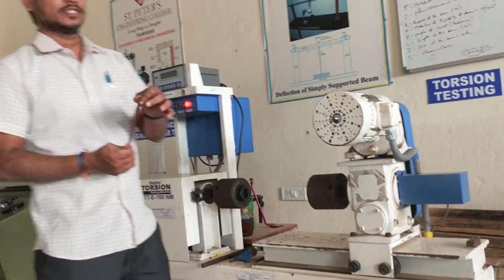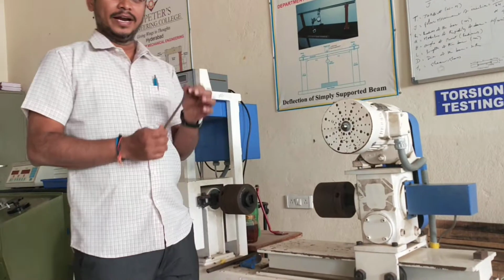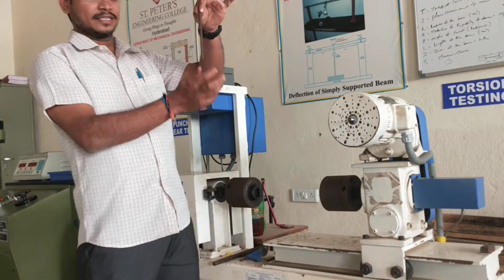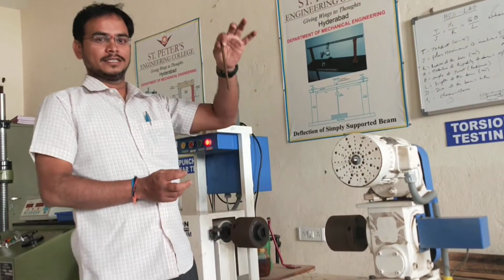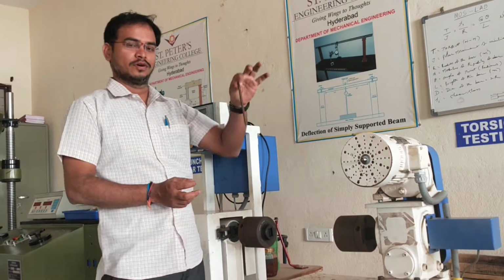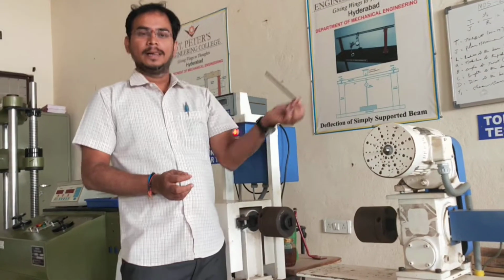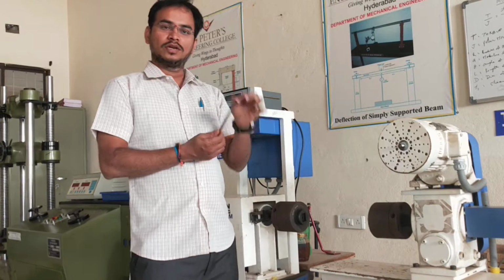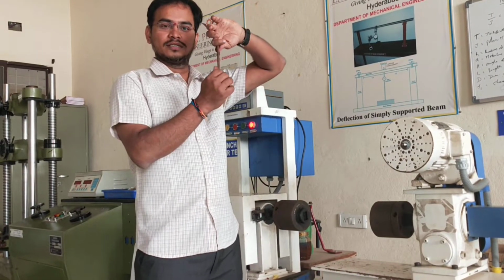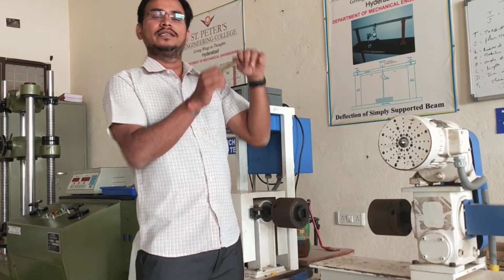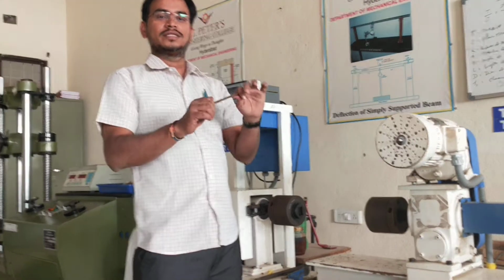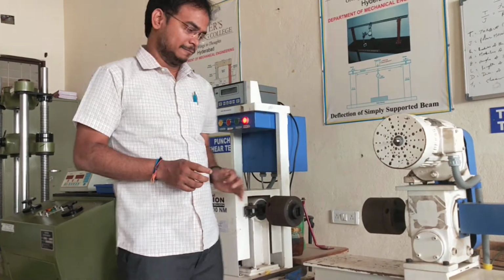When do we get the question of modulus of rigidity? When the shear forces are existing, when they are coming into picture, then only we go for the modulus of rigidity for designing the materials based on the type of loading. Here, if the type of loading is creating the shearing of the material, then we design according to the modulus of rigidity of the material.